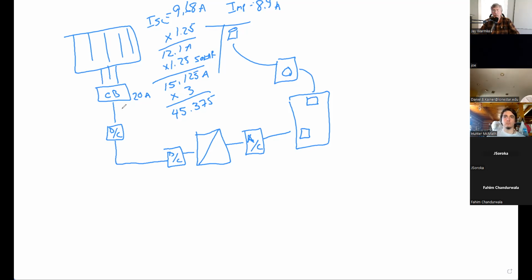Okay, so would we use 8 gauge wire and just go with a high temperature like a THHN? If that's in the third column, that has a rating of 55 amps. Well, in theory, you could do that. But one of the recommendations that I will make very strongly here is you only take the ampacity from column 1, regardless of what kind of wire you're using. So even though if we're using THHN and it says I have an ampacity with 8 gauge of 55 amps, I would take my reading from the first column, which means I got to go with 6 gauge wire, not 8 gauge wire.